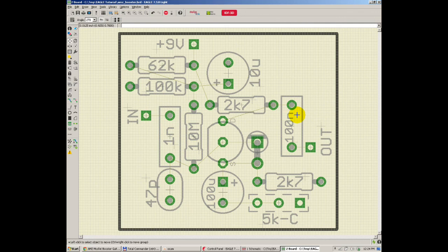Okay, there are some pitfalls before you start and route your PCB. There are some pitfalls that should be avoided. First of all, when you are going to run the route command, the default layer is top, so I would go and change this to bottom first of all.